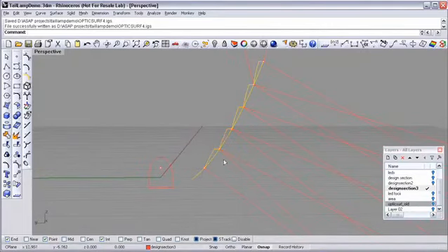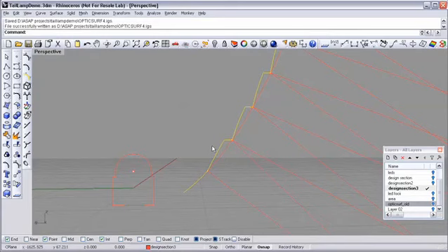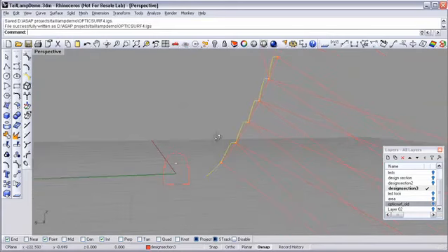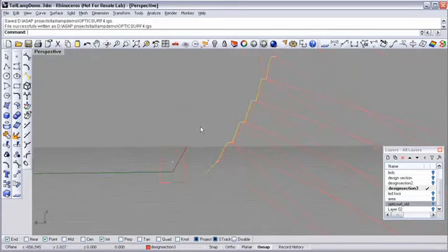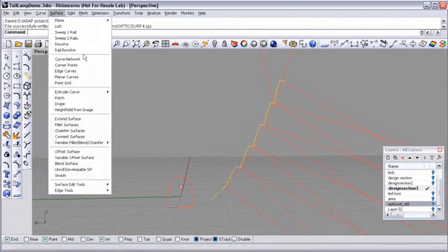Again, we have our base parabolic curve that we were working on, and then I've reconstructed the segments to direct the light. In this case, I'm putting a little bit more left-right spread, so you can see the surfaces have been tipped a little bit. The process to check this one would be the same as we followed before.